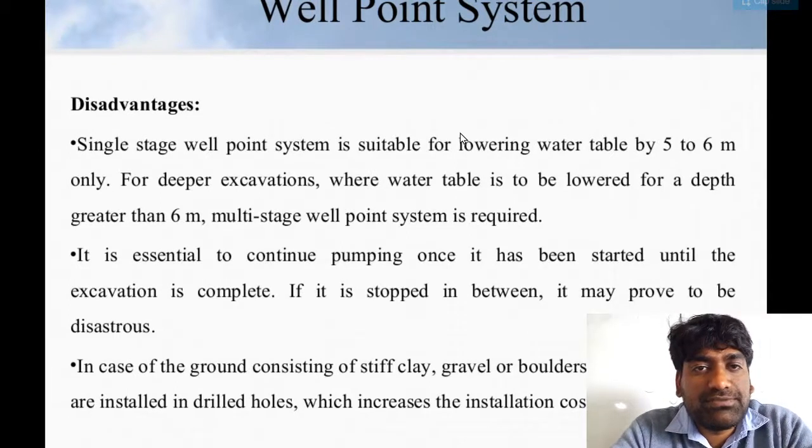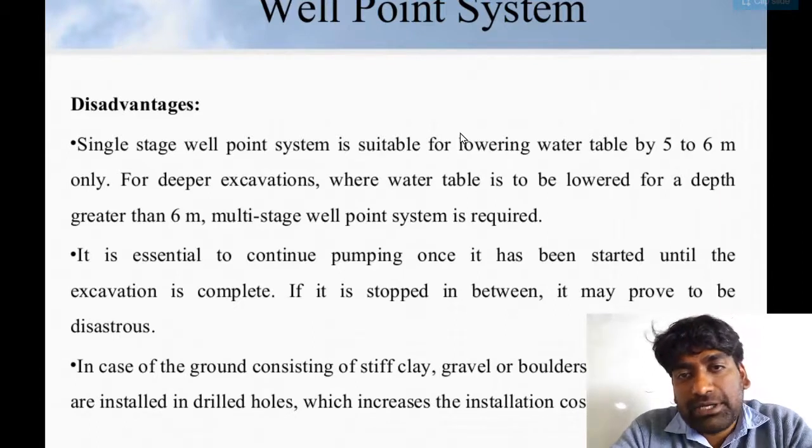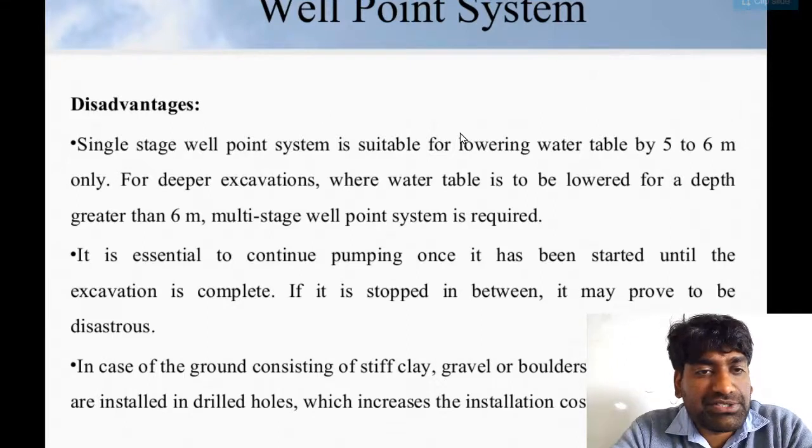Disadvantages: a single stage well point system is suitable for lowering the water table by 5 to 6 meter only. For deeper excavation where the water table is to be lowered to a depth greater than 6 meter, a multi stage well point system is required. It is essential to continue pumping once it has been started until the excavation is completed. If it is stopped in between, it may prove to be disastrous.